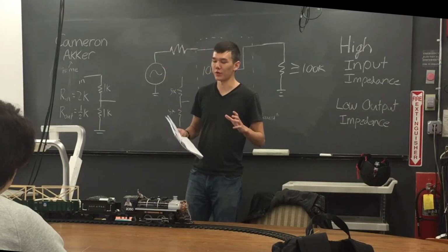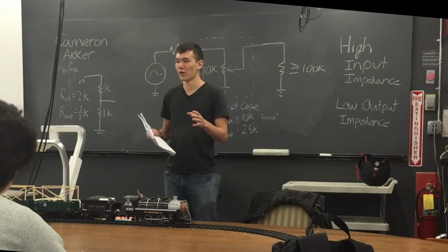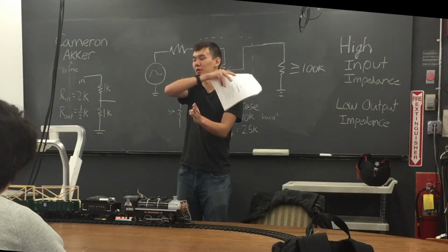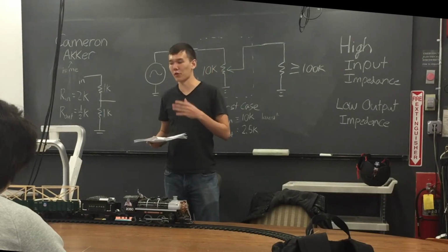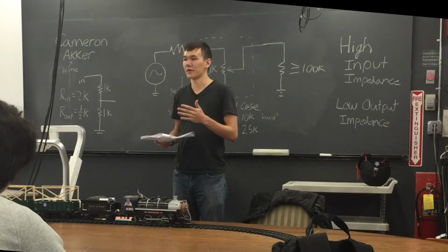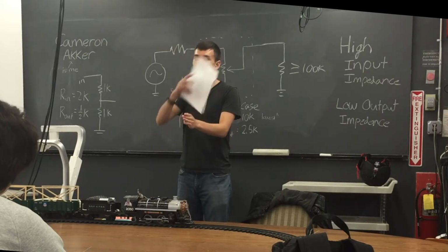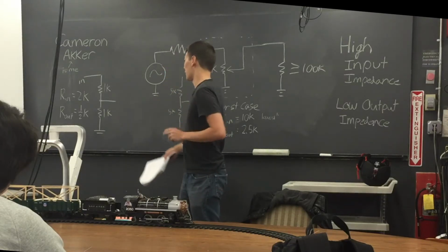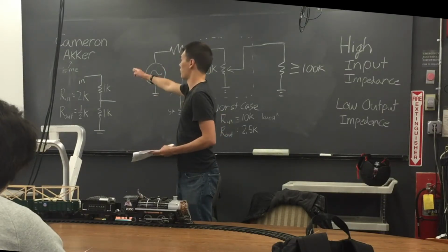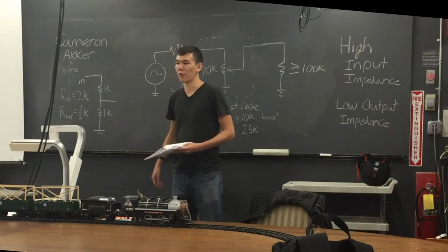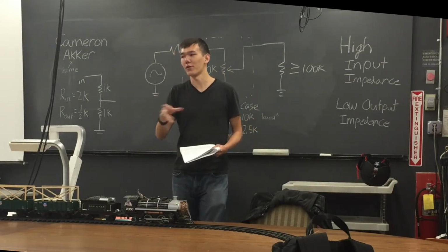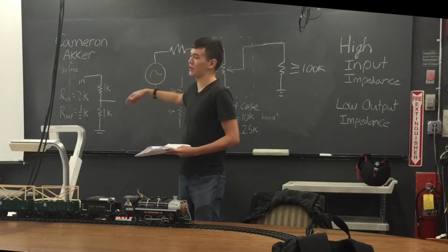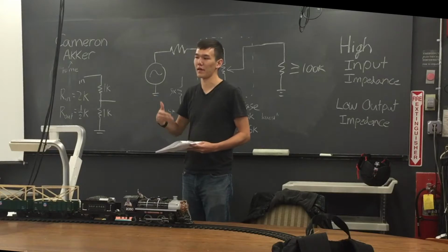very often in electronics, your power source isn't a perfect power source. Where you're getting your voltage input into a system has a bunch involved within it. And when you put a load on there, in ideal electronic design, you want to be able to put any load on there and not affect what's supplying the voltage. In other words, if I have this voltage divider with 10 volts on top, so I'm outputting 5 volts, I want to be able to attach that to, in a perfect world, 100 ohms and have it still be 5 volts and get however many amps that is. I'd be able to attach 100K and still get that same 5 volts.